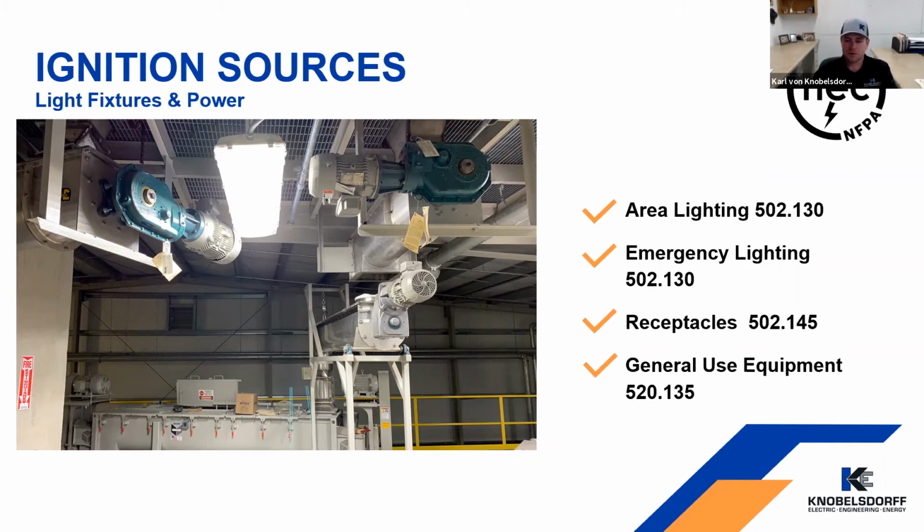Receptacles are covered under 502.145. This is one that's also missed a lot in facilities. They don't make a Class 2 Division 2 receptacle. They only make Class 2 Division 1, which are your twist lock, make before break receptacles. So you have to use that type of receptacle in both a Class 2 Div 2 and Class 2 Div 1 location.